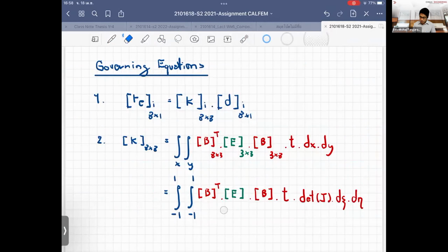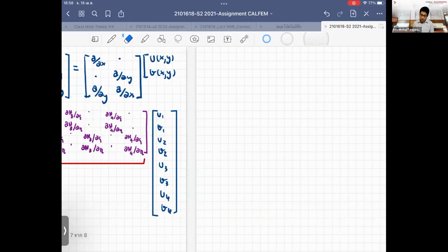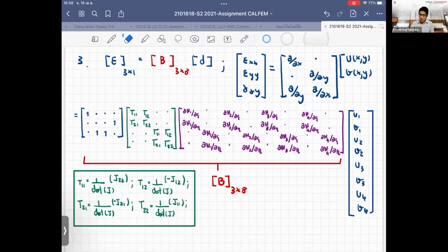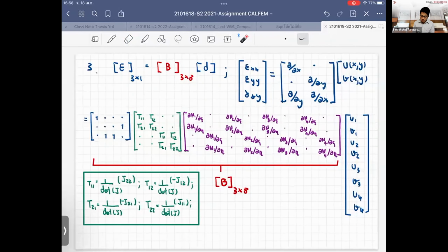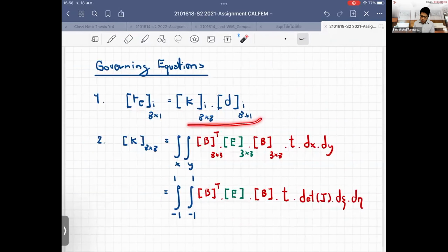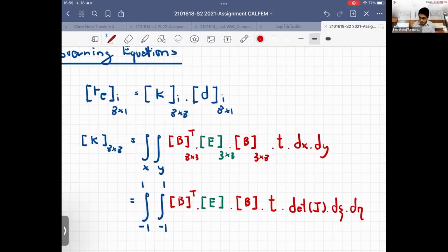Okay, and we use the Gauss-Point integration rule. I'm not going to emphasize what is meant by the Gauss-Point integration rules, because I think you may have learned before, otherwise it will take a bit of time. So we need this couple of the matrix. Once again, have a look. If we go to step 1, this is the basic formulation we need in our analysis, which is force times the stiffness matrix of the element, and this belongs to element I, for each generic element.